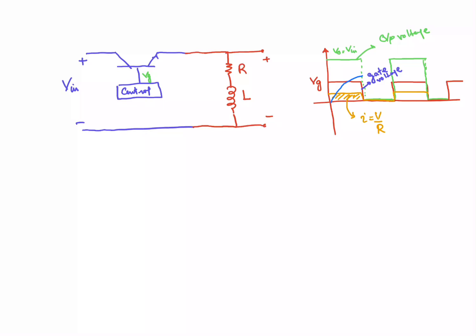And once you turn off your switch, now what will happen? The energy has been stored in this inductor, and that energy is equal to half L i square. And what was the inductor voltage polarity? The voltage across the inductor was like this, when the current flows in this direction, starting from the source and completing the path through the load like that. So when the energy is stored, this inductor is acting as a load at the moment, and it is storing the energy in this interval of time. So energy stored is this one.